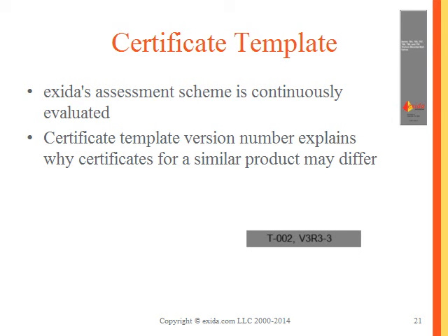And you may see, let's say, two ball valves, both certified by exida, but the certificates may look different. The simple explanation for that is they may be different certificate templates. Look at that certificate template number. That would explain why they are different.